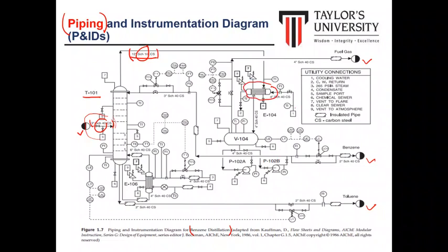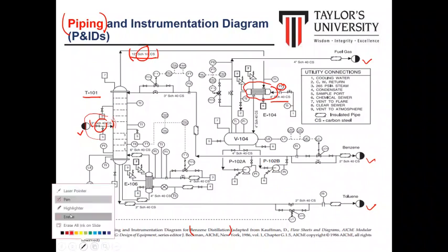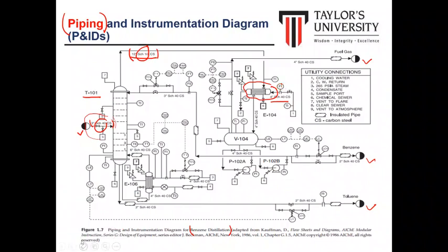This is the inlet for the cooling, which uses 4-inch schedule 40, and we install the flow indicator. FI is the flow indicator, which is the instrumentation mounted on the equipment or piping. So the flow indicator is mounted here. You can see here, this is the symbol of FI.